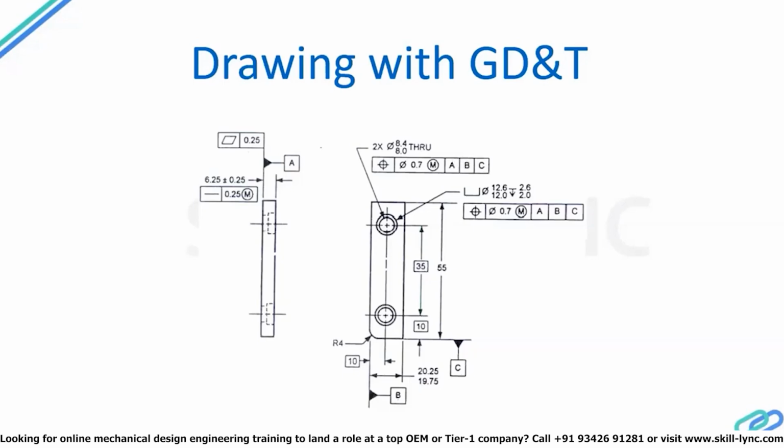If you use such a method, we can think about the same example that we were discussing in the last slide. I'll just touch upon the inspection point alone. You can see in this feature control frame, for inspecting this particular hole, we are saying the primary datum to be considered for this hole should be, in all cases, datum A, that is this particular surface. What we are trying to say is you should always rest this feature first in your inspection. So now we are clearing out the ambiguity in inspection. You should not use any other surface to rest the part for inspection purposes.